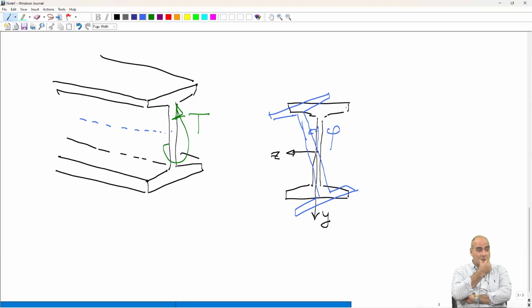But imagine that you have a beam, the beam that we have seen before, the real beam, which comes on the track with two forks like this. The cross-section at the forks cannot rotate because the forks forbid them from doing that. But they can freely warp because they are not constrained outside of the plane.